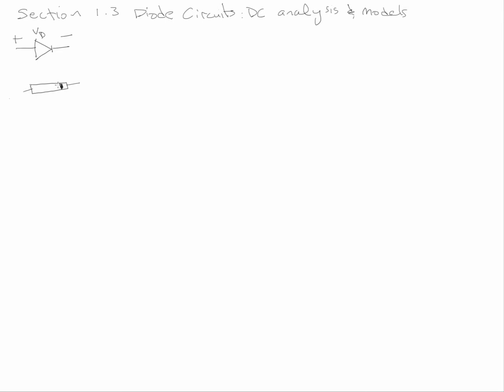It would look sort of like a cylinder with a stripe right here. When you're building a circuit yourself, this stripe matches that vertical line in the symbol. So this is your P part, this is your N, this is plus and minus for a forward bias diode. Something I looked up too: we talked about the varactor diode previously, which was used to make tuned circuits, and it has this symbol here, which shows that you can tune it via that capacitance.